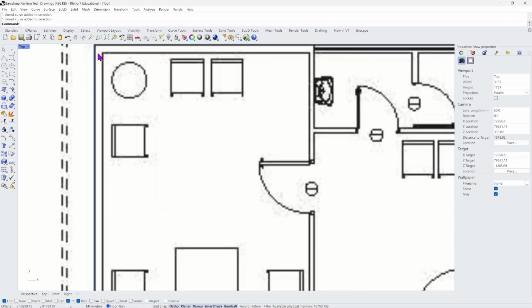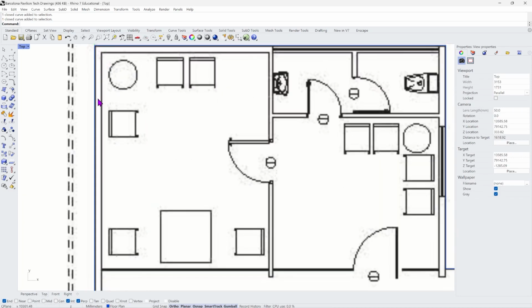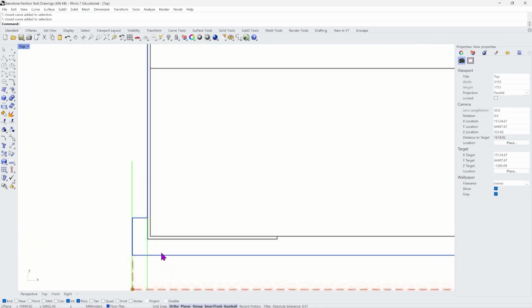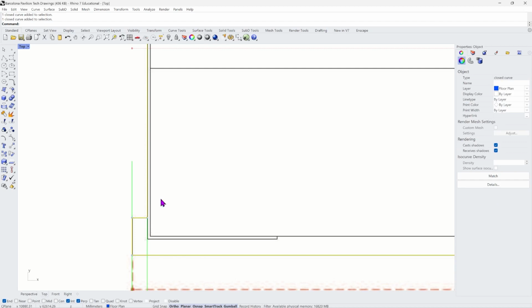We can see that in some places we have a wall thickness, and the easiest way to do that will be to use command offset. So for example, quite commonly when you have your outline of your drawing, you will need to have a second line that's going to be creating the inner part of your walls, and usually it's a consistent wall thickness. So offset will be a really useful command. If you used AutoCAD before, it's exactly the same command as well.